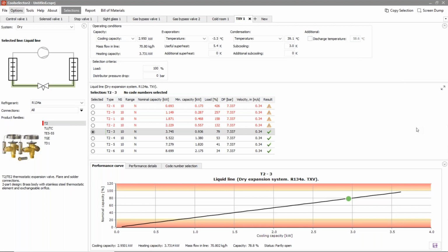Then the next question, Carlo, is how can we get a load calculation sheet for cold room selections? I mean, to take printouts, is that possible? We don't have certain heat load calculations today, but I recommend using the one we have in the Coolselector, because it will give you the heat load calculation by entering the cold room dimensions and all the loads involved.